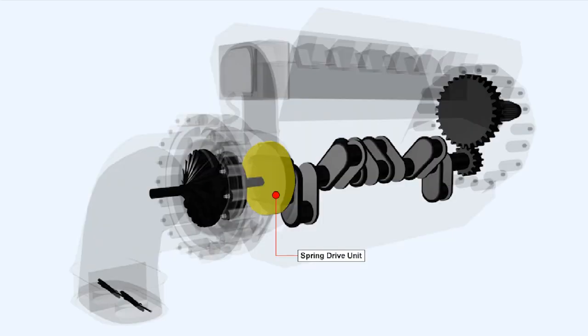Notwithstanding the lightness of the compressor impeller, because of the high rotational speeds at which it operates, up to 25,000 RPM in some cases, the inertial forces generated during engine acceleration and deceleration are huge. To minimize the inertia stresses in the impeller drive, some of the systems incorporate a spring drive unit. This transmits the drive through intermediate gears to the impeller pinion, and limits the high torque impulses transmitted to the supercharger impeller during high rates of propeller engine acceleration or deceleration.